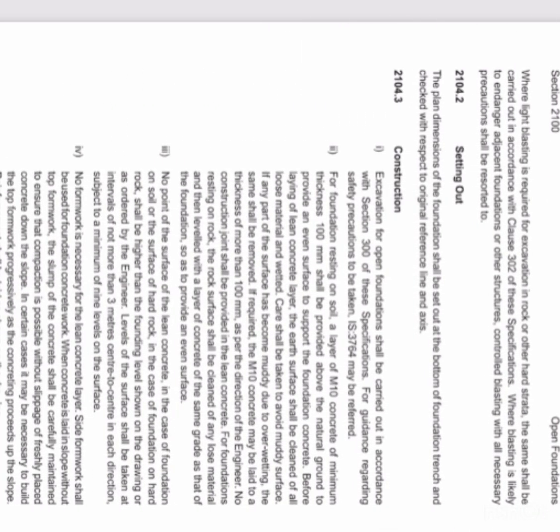Setting out the plan. Dimensions of the foundation shall be set out at the bottom of the foundation trench and checked with respect to the original reference line and axis. Construction. Excavation for open foundation shall be carried out in accordance with the section 300 of the specifications.